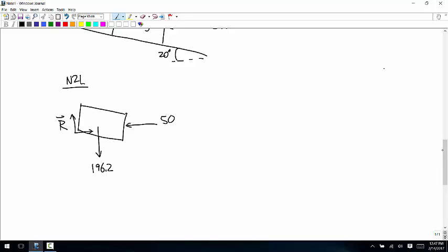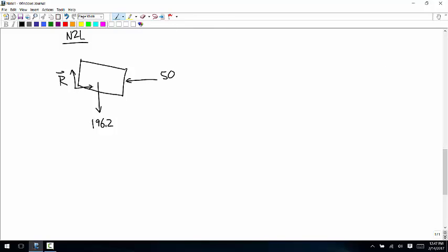I think this was the one where I mentioned that you could use a rotation matrix for this. So yeah, you could use a rotation matrix that goes from this coordinate system to one that's aligned with the incline. In order to rotate from this to this, that's a clockwise rotation of 20 degrees. So your theta is negative 20.